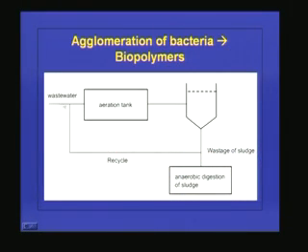You can see the wastewater is coming here, and this is the aeration tank. Here what is happening? We are giving a lot of oxygen. So under aerobic conditions, the organic matter is getting converted to carbon dioxide, water and new cells. And from the aeration tank, the entire liquid is going to the secondary sedimentation tank.